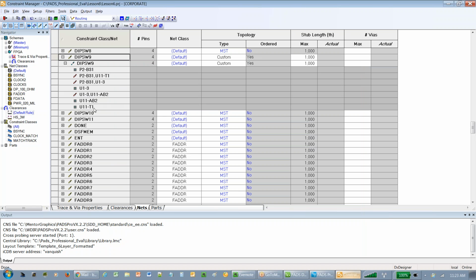So you as an electrical engineer have a lot of control over that type of definition without relying on passing that information along to the PCB designer. And he'll see the netline ordering when he places the parts if he puts the part in the wrong spot. Also very useful for design reviewing the board, so you can see where the pin pairs were routed correctly or not. As another advantage to this, you can define what we call virtual pins.